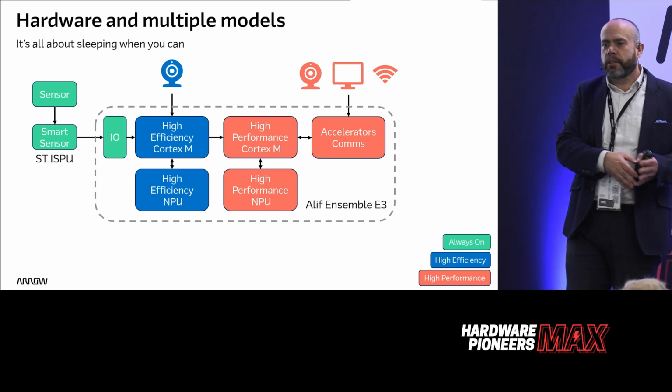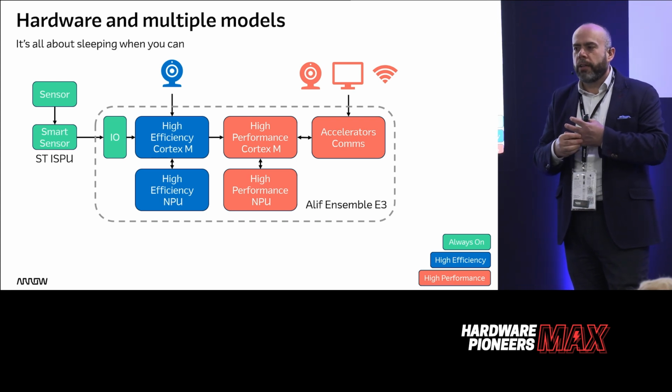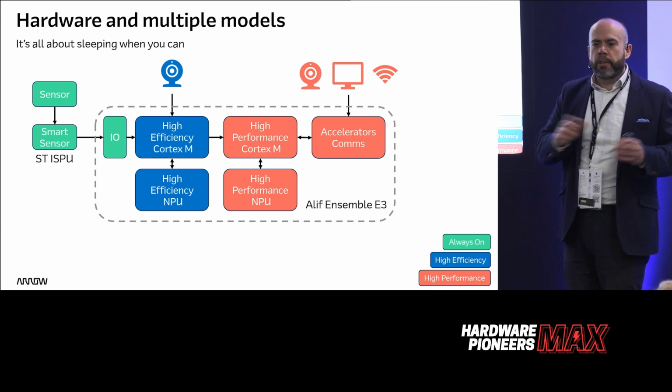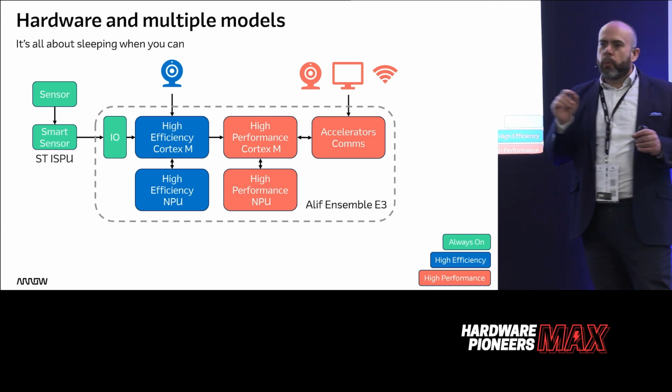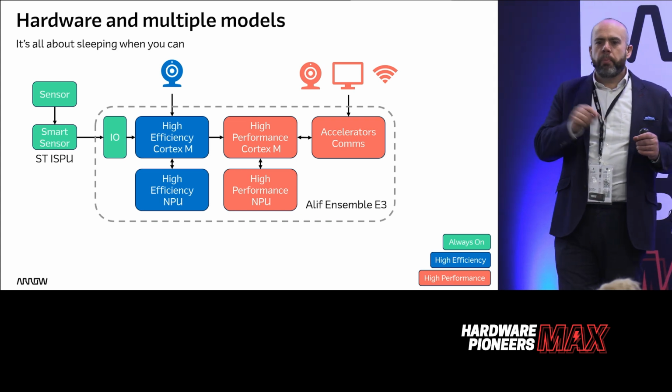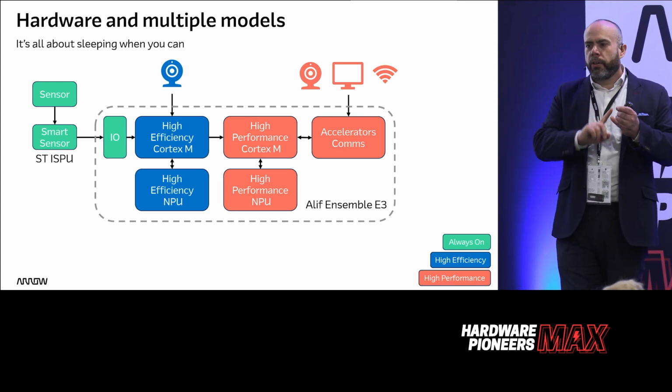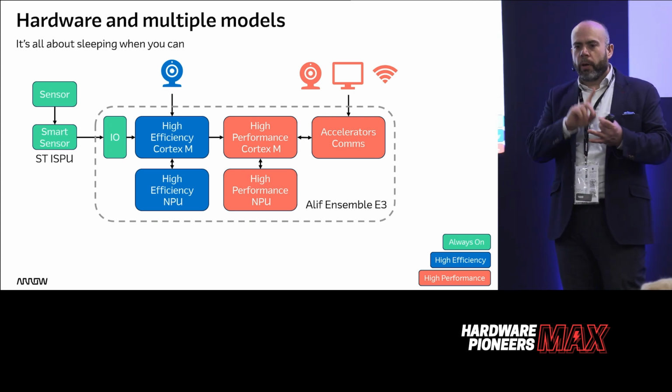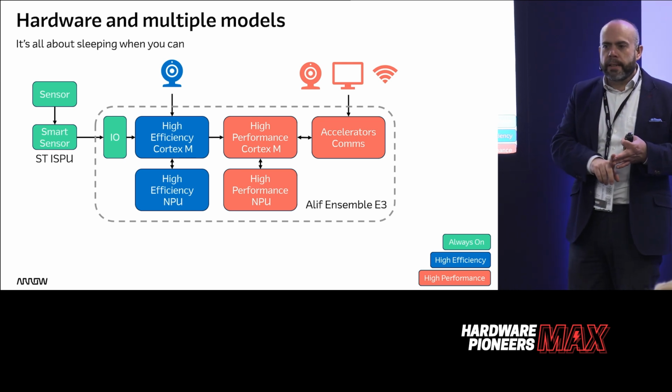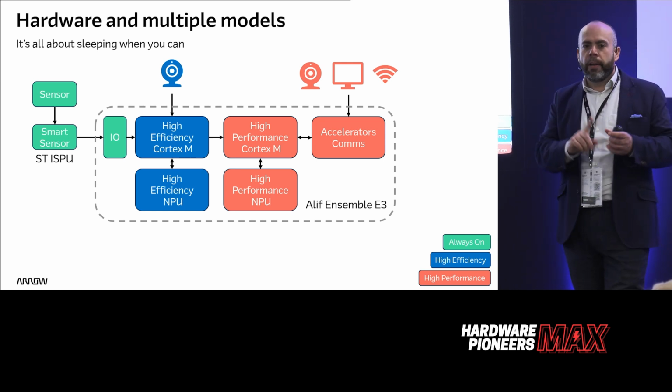battery operated devices. I don't work with watches or smart rings. My thing's going to be plugged into the mains. It doesn't matter. I would caution you that if you can reduce the power budget of your device, then you're going to have a smaller PMIC, a smaller inductor, smaller heatsink, maybe no heatsink, maybe no fan.